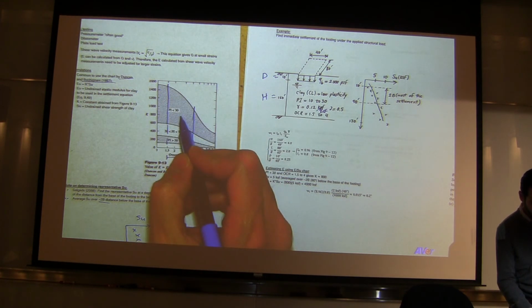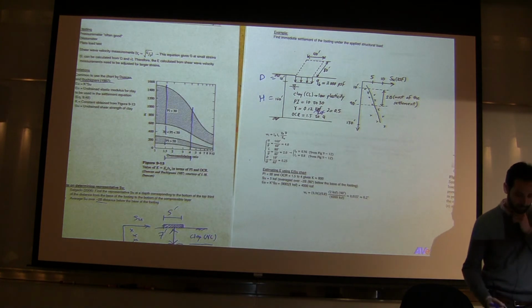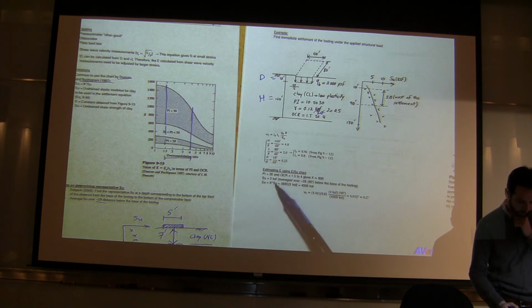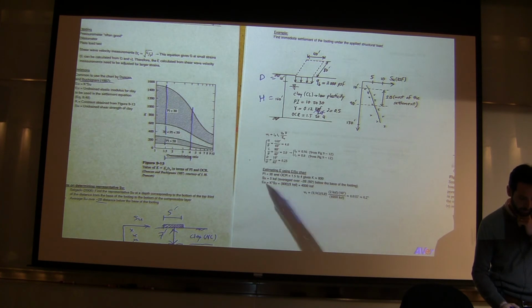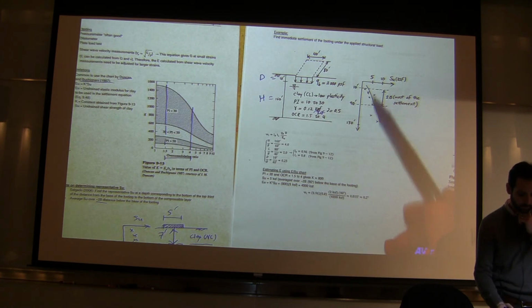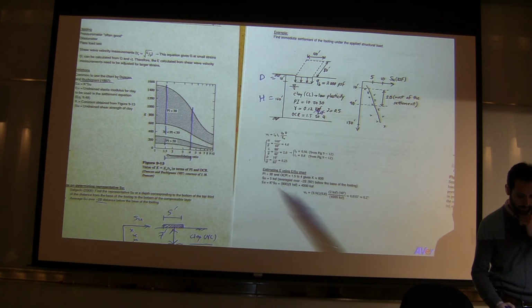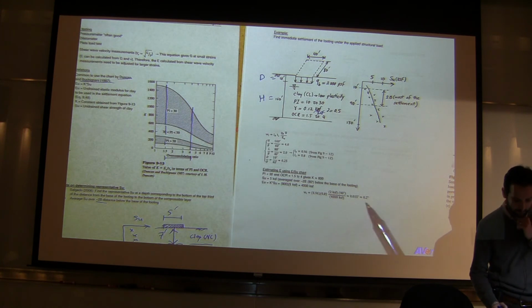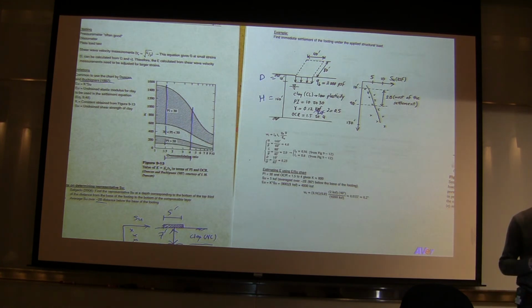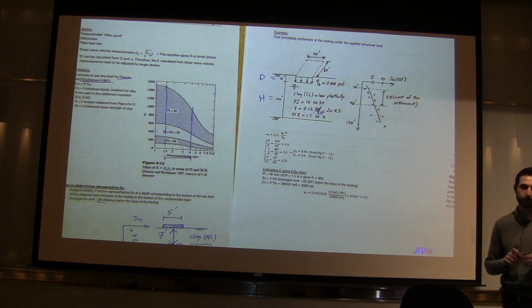Like maybe 800? 800, yeah. 800 sounds to be pretty good. So that's what I've used here. So 800, and then SU, the average SU was 5, so you multiply that 5 by 800, and that gives you 4,000 KSF. You plug it into those equations, and that gives you 0.2 inch of settlement. Immediate or total? Immediate.